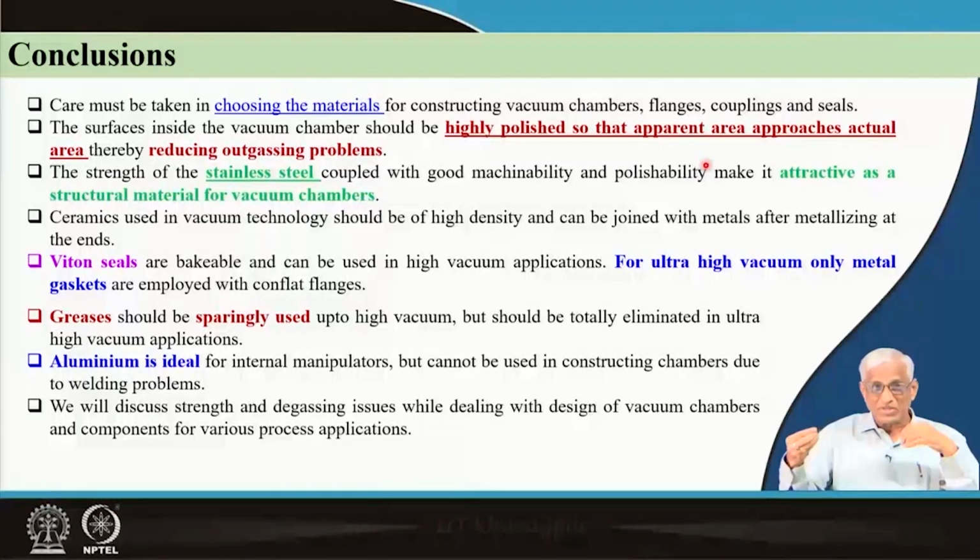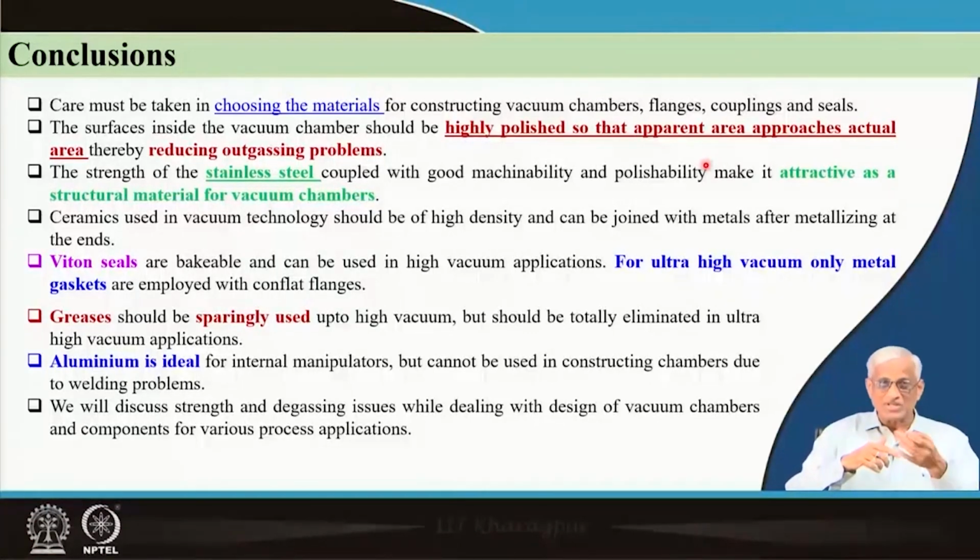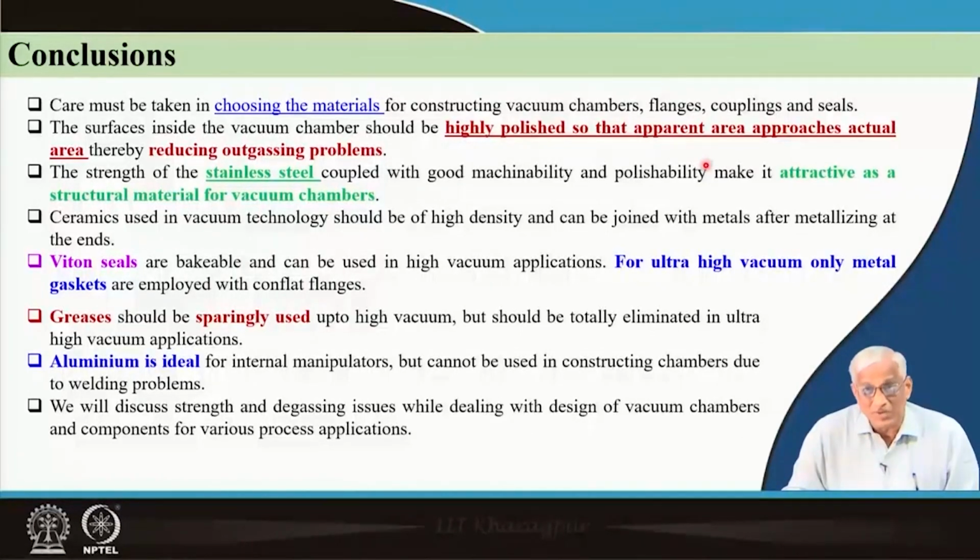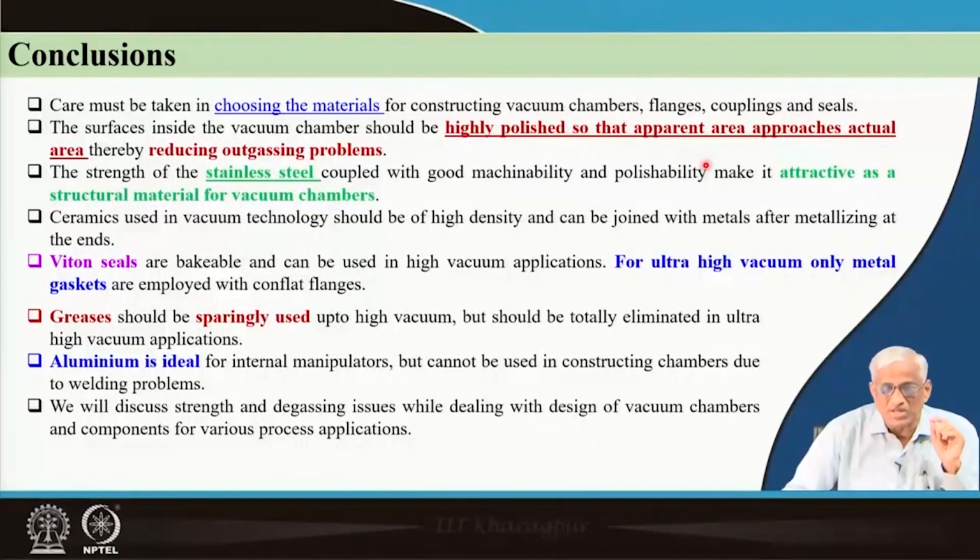Some amount of chromium comes out, and the rest of the area becomes deficient. So, when to use high carbon steels and when to use low carbon steels, that needs a metallurgical or mechanical engineer with a good idea of machining and welding. These fabrication issues we will see in the next class, because fabricating vacuum components and vacuum chambers is not the same as high pressure components, and outgassing properties have to be chosen.